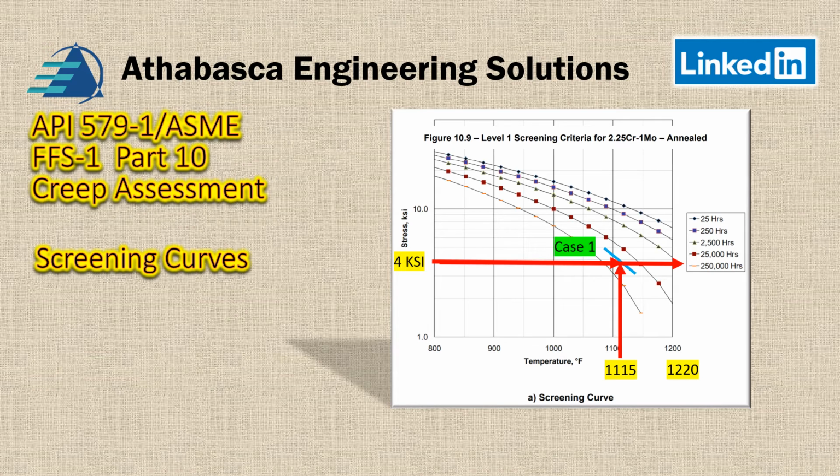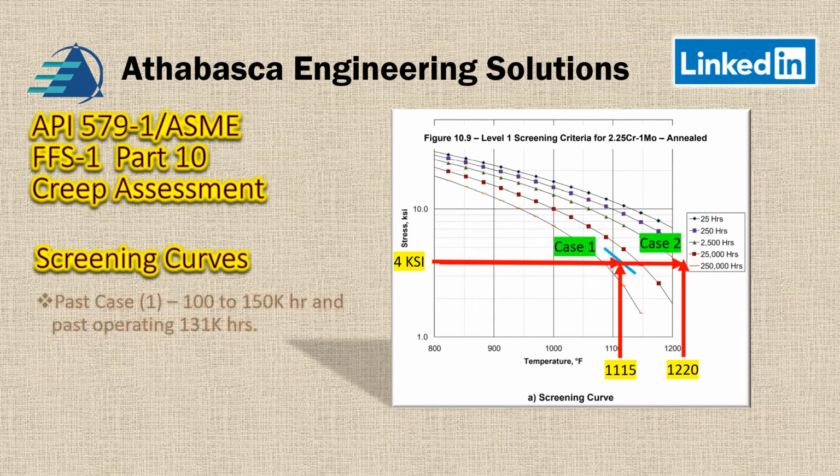So let's summarize that. A past case, which is case 1, we basically got 100,000 to 150,000 hours in a life, and we've used 131,000 hours. So we're approaching the end of the service life for these tubes in very general terms. And because in case 2, with that excursion case, we're running over 1200 Fahrenheit, therefore we're looking at a more in-depth analysis to determine what we can do with that.